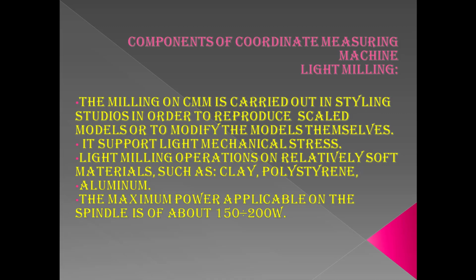And this is the basic thing, how much power this machine could take to be run. It shows that the maximum power applicable on the spindle is about 150 to 200 watts. Spindle, you must know about that. It is a rotating shaft; on a lathe machine you can see the spindle on its bed, and in many other places. So you can correlate the spindle and the power.